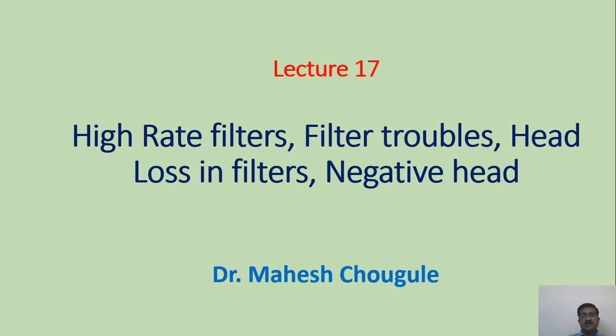And along with the filtration process, the filter troubles have to be studied, so that how to overcome this also has to be studied properly. Then we'll have to study the head loss in the filter and negative head also. So let's start today's session.